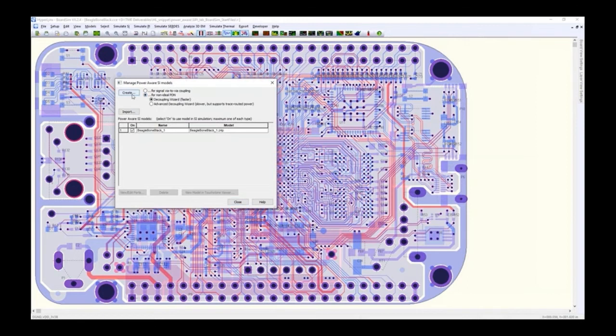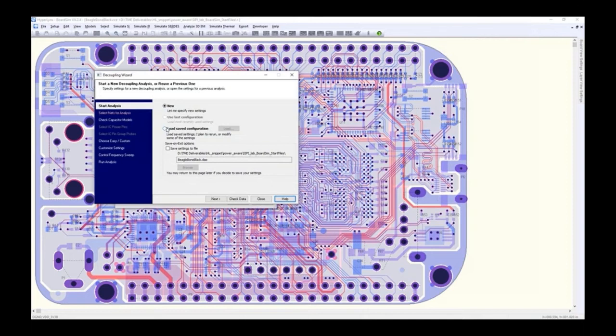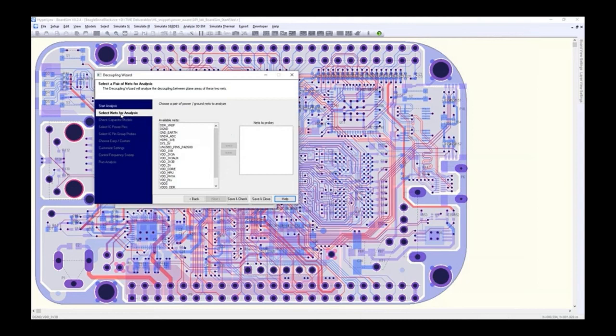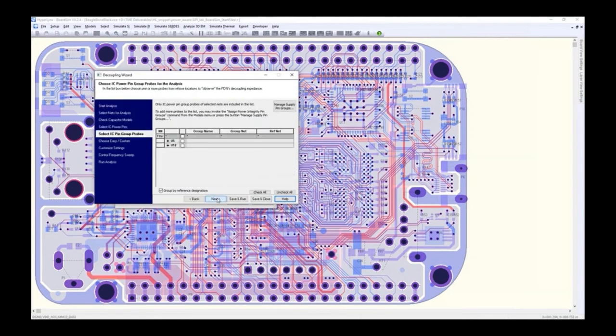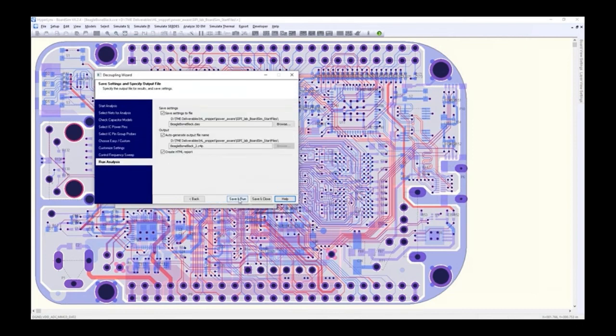in your design. A power-aware SI interconnect model is an S-parameter model that the software creates with port mapping information with respect to the IC power pins and all signal vias. The software enables you to automatically connect the model to the IC pins or vias using the port mapping information on the board design.